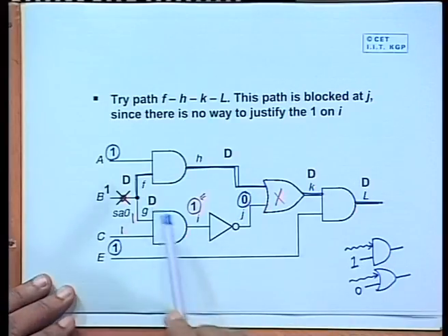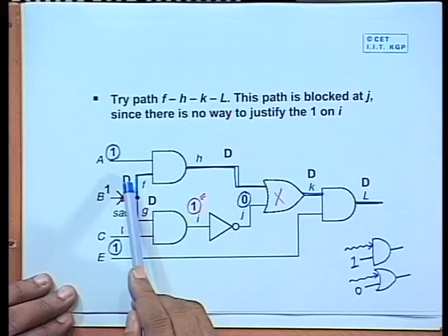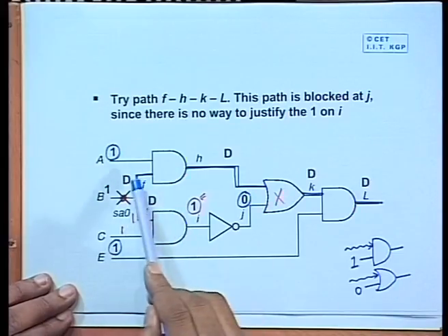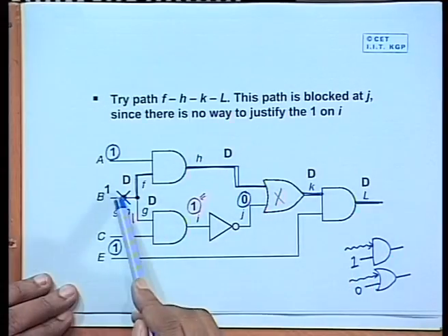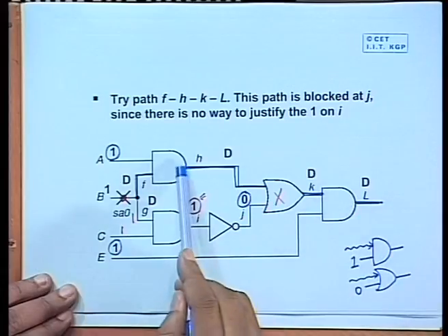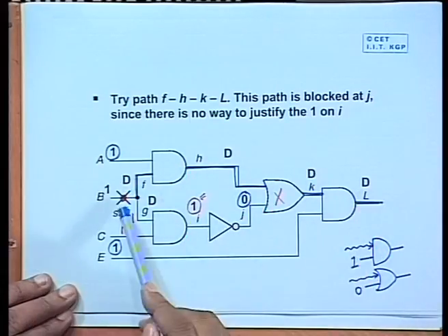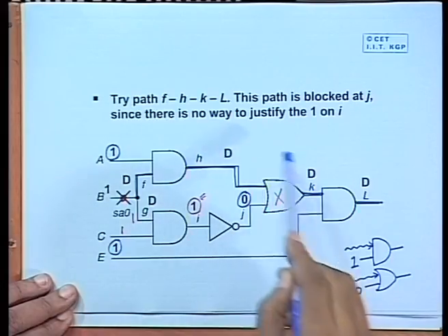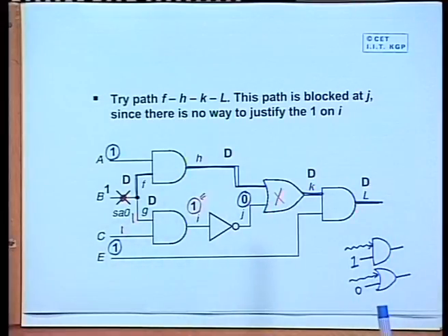Now, here you observe one thing, the change here we were indicating by D. So, D through an AND gate, there is no inversion, 0 to 1 becomes 0 to 1, D, D and D. There are no inversions in between, no NOT, NAND and NOR. So, D does not become D bar. So, any 0 to 1 change here will be reflected as a 0 to 1 change here, 0 to 1 here and 0 to 1 here, they all remain D.